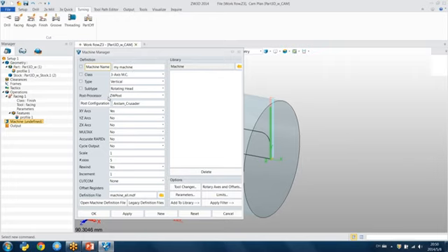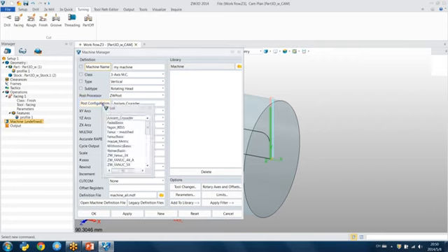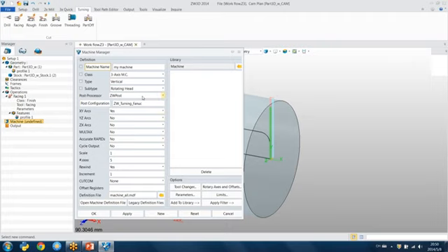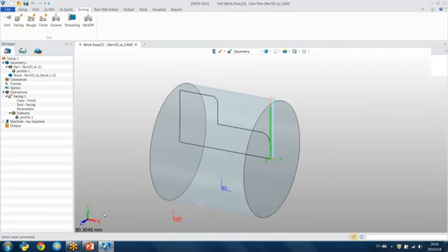In the machine, you need to choose the right post process. ZW3D supports turning and blank. Press OK. So after you choose the machine, next you need to output the NC code. You can right click and insert NC, and drag the operation into the output setting.